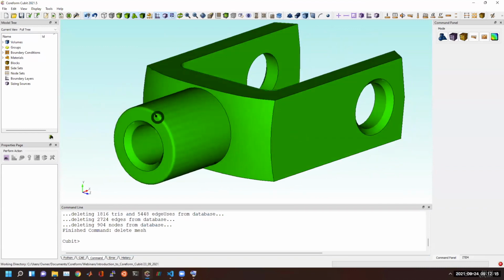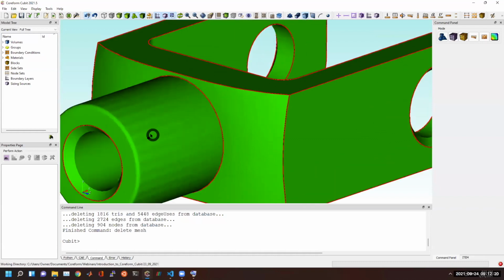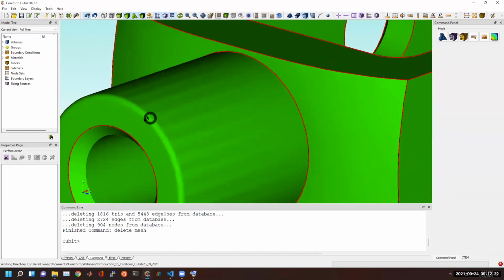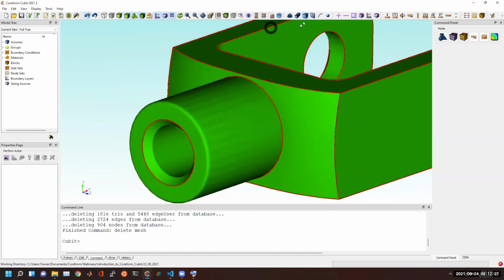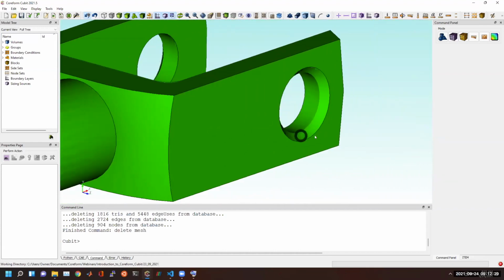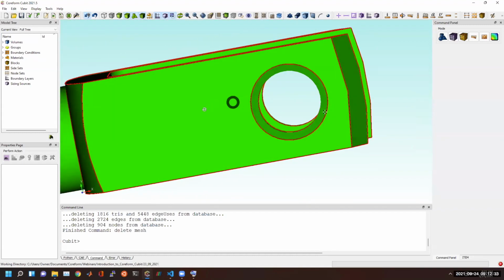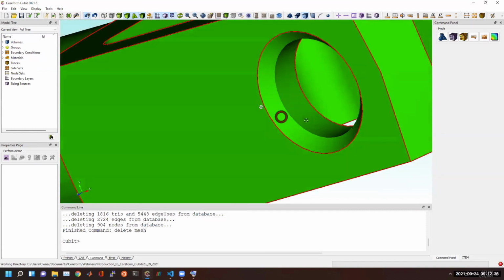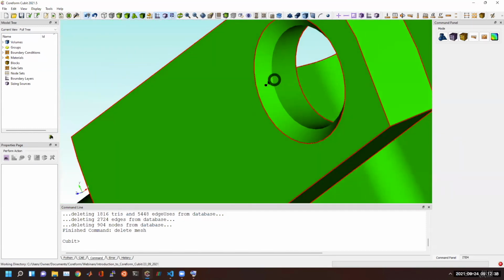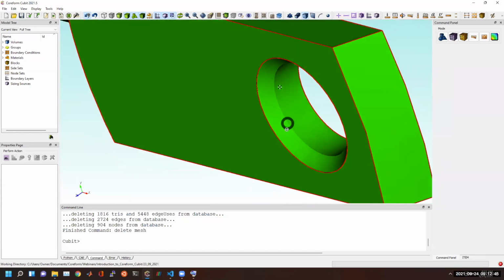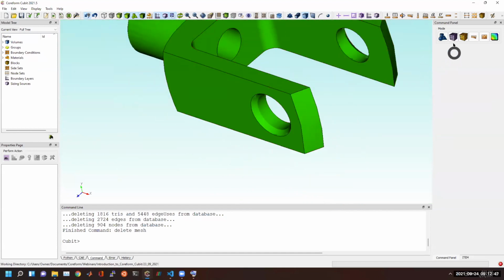And so what you'll see is that for this STL file, this fillet doesn't have bounding curves because that wasn't a feature angle, because the angle here is 0. But everywhere else, there's these black curves for these surfaces. And that feature angle means that it couldn't identify that these two surfaces, of what we know are two surfaces, were separate. So if you wanted to find those, you could just decrease the feature angle and it would find those.